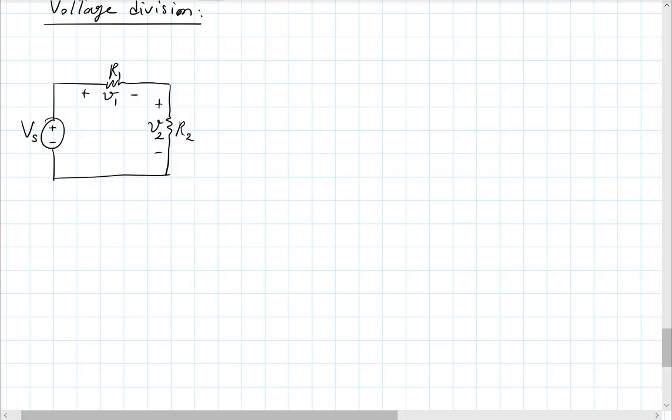well, you can simply solve this circuit and you get the current, which is Vs divided by R1 plus R2, and then multiplied by R1 will give you V1, and multiplied by R2 will give you V2. Okay, so a very simple circuit to solve. And thinking of it from the equivalent resistance point of view, calculating I should be very easy because I have two resistors in series. As far as the outside is concerned, they just add up. So I is simply Vs divided by that combination.